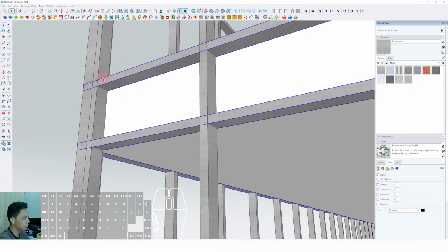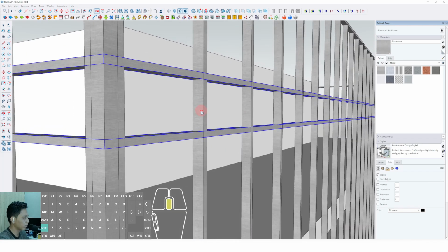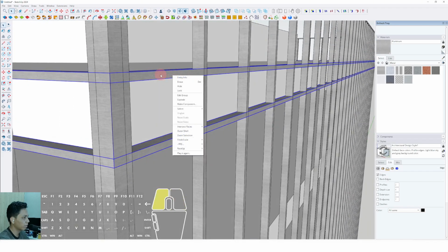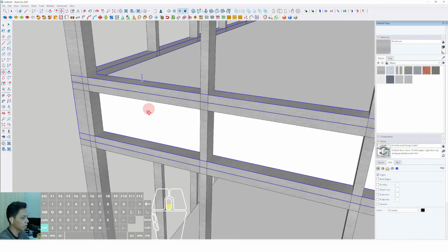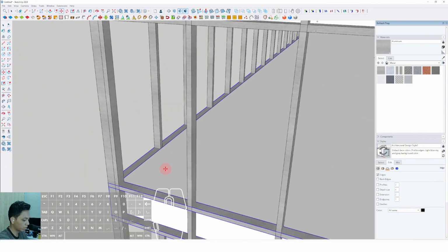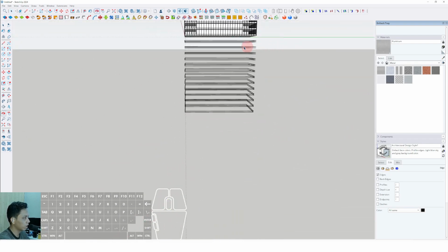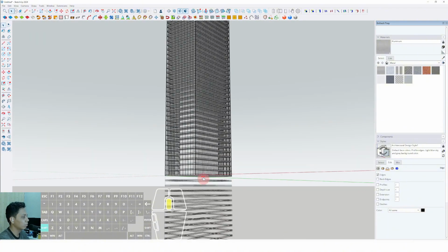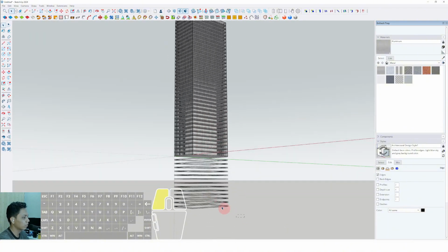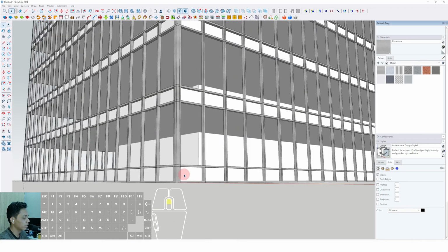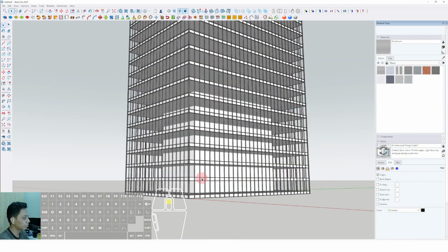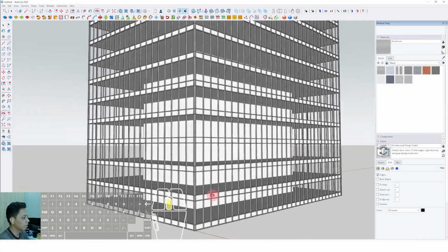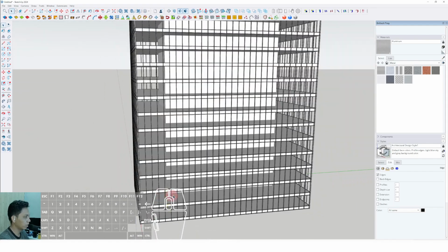And don't forget to click both of the horizontal frame, right click and make group. Okay, and just select move tool, press Ctrl, click to this surface, place to this position, then we can type x50 for example. So we can delete the unnecessary object. We can delete the unnecessary horizontal frame here, just delete it. And okay, we can select the another material.